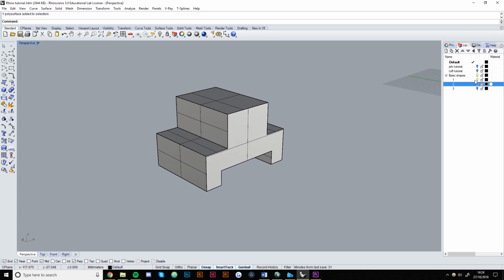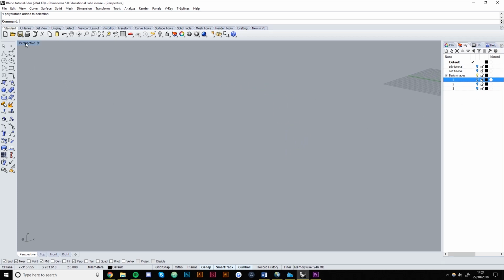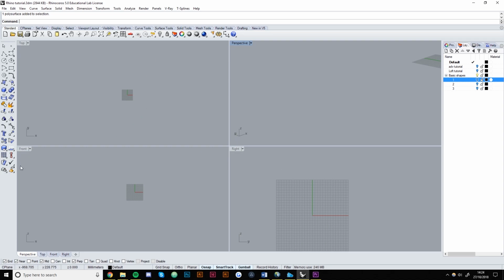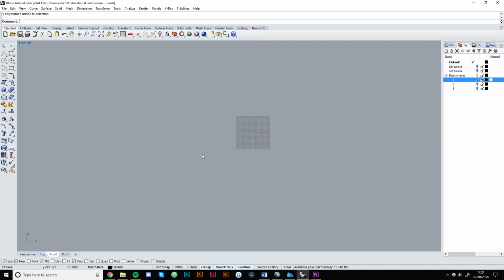To model this shape, the first thing that I would do is go to the front view. You can also do that along the bottom left. Once in this view, we'll use the curve tool, and we're going to draw out about half of the shape, and then we're going to mirror it to create the full general shape of the object we're modeling.